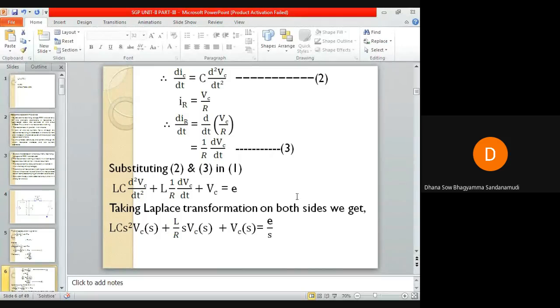Okay, so you know what is IC. Just differentiate it with respect to dt. So d by dt of IC is C into d square Vc by dt square you will get. Consider it as equation number 2.